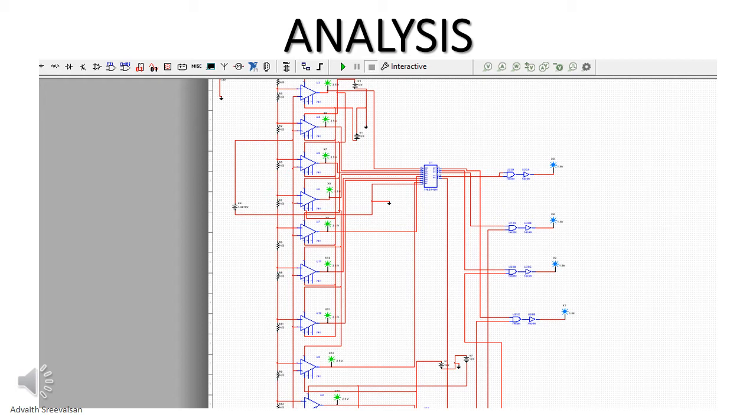The outputs of the comparators are connected to two 8:3 priority encoders since we don't have a 16:4 priority encoder. Using two 8:3 priority encoders, 4 NAND gates and 4 NOT gates, the final output is connected to a blue probe to know the output. In this figure, we have applied 1.8 reference voltage and 1.687 as our input voltage and get an output of 1111. It is shown by the yellow probes, and the blue probes are turned on.